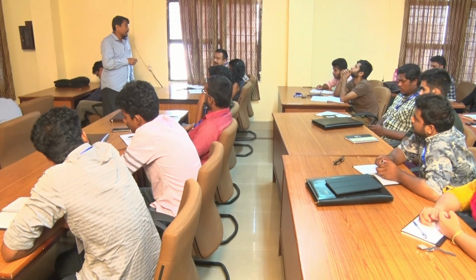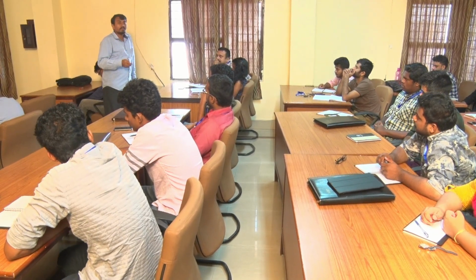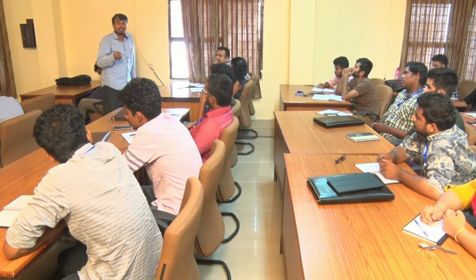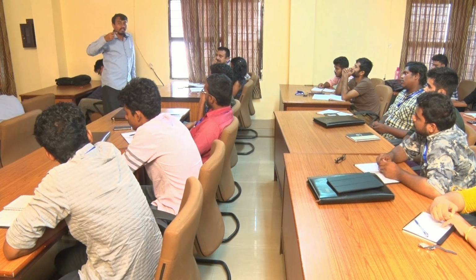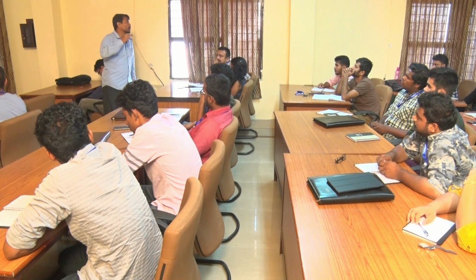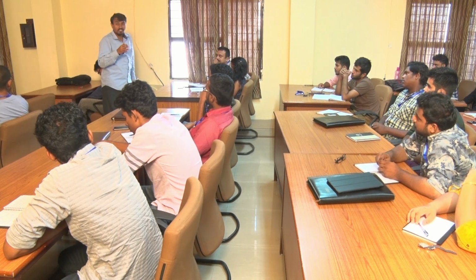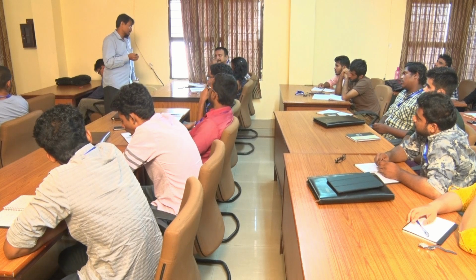First, estimate the parameters objectively. Then, after coming up with the RMR index, calibrate with the old database. If the database gives you positive feedback, then yes, you can proceed. But if it gives contradictory results, you have to go for a third option.